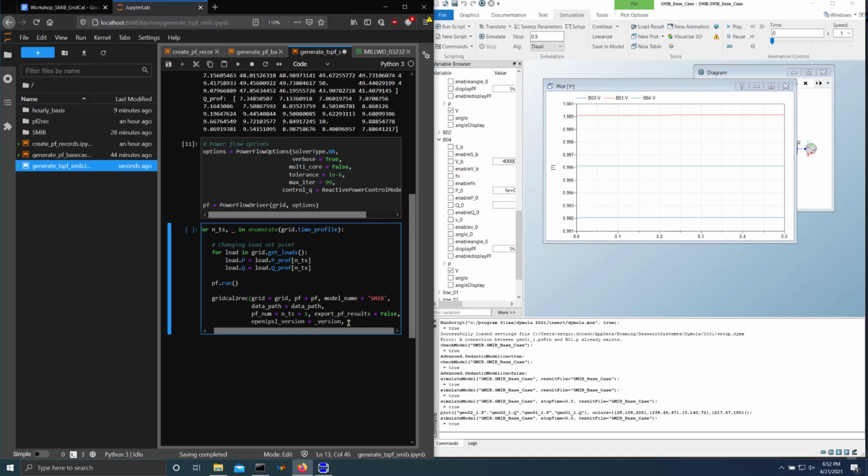because we are actually doing a time series power flow computation. So here first we will indicate with a flag that this is a time series power flow by changing is time series to true. And we will pass a name that is the name of the time series computation.